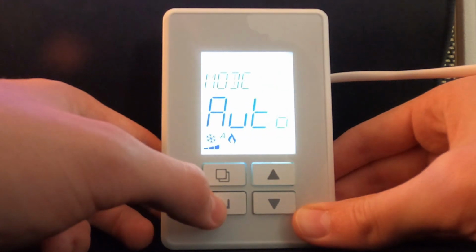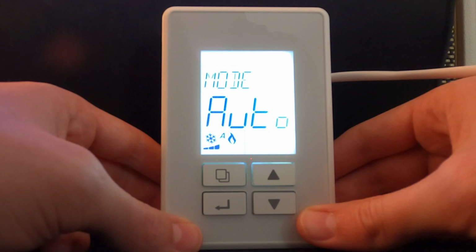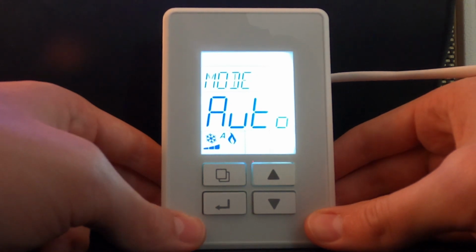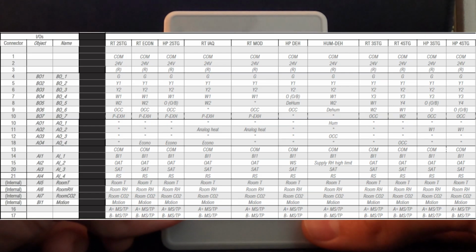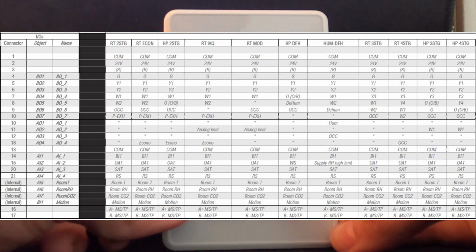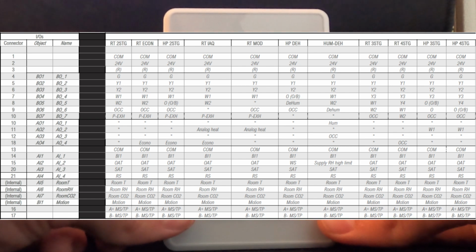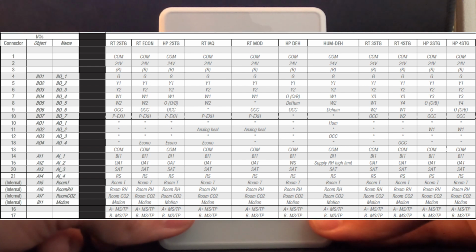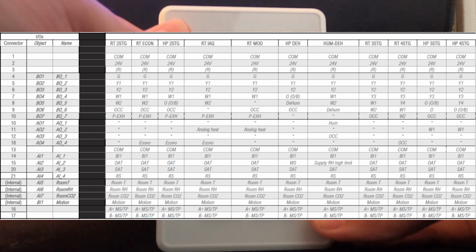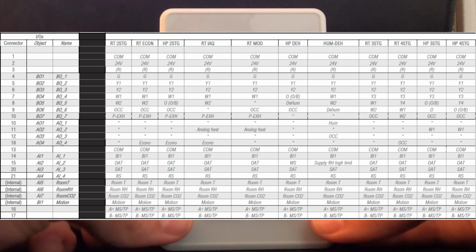Okay, so now we're powered back on and we're back running that same program. One thing I would like to mention is that, especially with heat pump, it's very important that you follow our wiring charts and diagrams in our documentation. Available on our resource site is the BW437 quick guide, which goes over all the different wiring diagrams, charts, things like that, to keep in mind that are very important, especially on the heat pump. That seems to be the one that we get the most confusion from with some customers on setting these up. So that would be my one recommendation, is to check those out.